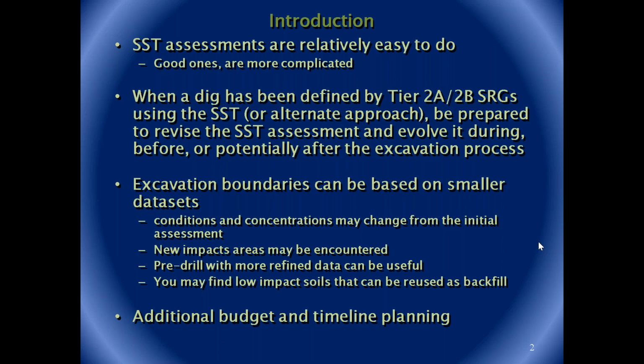So when your dig is defined by Tier 2A and Tier 2B, you can use alternate approaches, but it becomes a little more complicated if you want to do major revisions during the process or after the process. That's one of the nice parts about the SST, because it's an AEP and AER vetted tool. It allows you to go right through to your excavation. You do it professionally, you've taken the course, you get your confirmatory samples, you close it up and go to reclamation. Whereas if you're going SSRA, you have to approach the regulators beforehand, show them how you're deviating from conventional methodologies and perhaps their policy, and get their endorsement before you proceed.